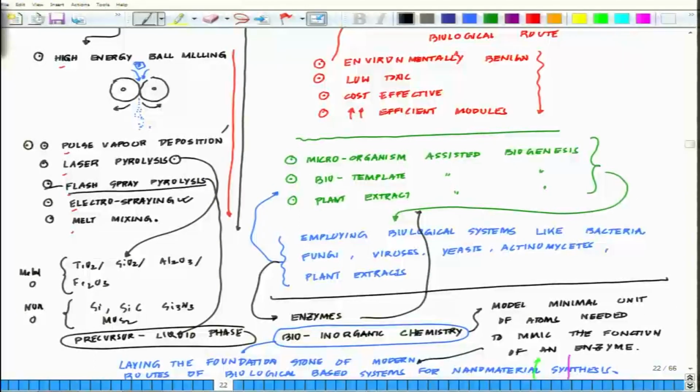Okay. So, coming back to the electro spraying techniques, what we are talking about. The electro spraying method is based on electromechanical device in which a mixture of solution, so it is in the liquid phase, containing the selected polymer and the solvent is taken up by a syringe and a high voltage is applied to the capillary tip that results in the production of charged droplets. Okay. The solvent is evaporated on its way to the counter electrode and particle or fiber are then collected at the end product. The electro spraying technique provides both flexibility and control of the surface parameters and electrospraying is one pretty neat process to produce nanoparticles.